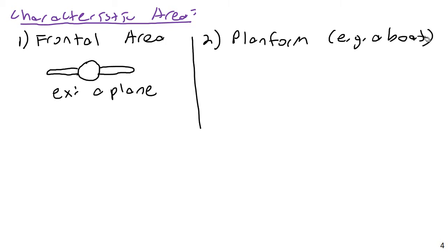So the reason that, in the case of an airplane, the forward cross-sectional area projection dominates is because it is traveling at very high velocities. When you're traveling at hundreds of miles an hour, the frictional or viscous effects are more minimal. And so what is really critical is the frontal inertial effects of the fluid striking the frontal surface of the plane.